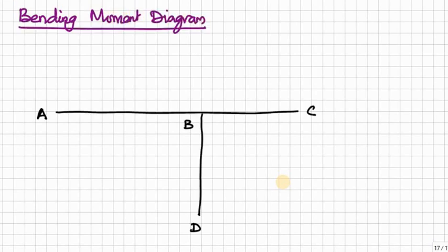Now the bending moment diagram. So this is the frame, and at first we have to note down the support moments. At A we have 7.72 negative, and at B, that is BA, plus 3.76, therefore up we have to note down and just join by a straight line.